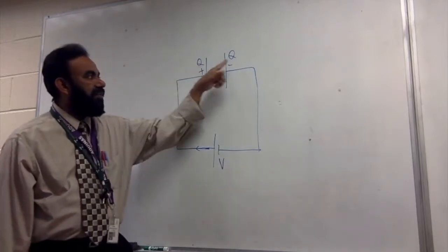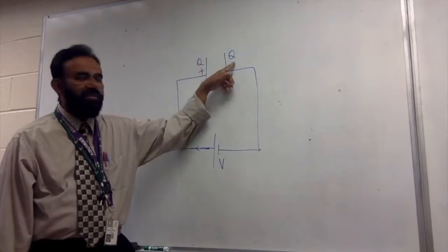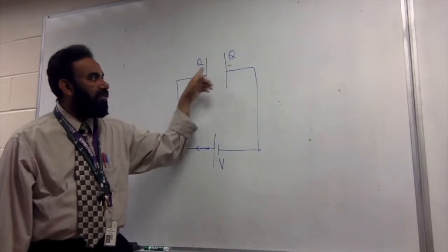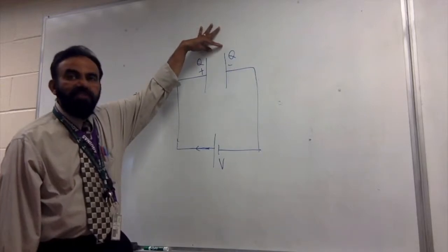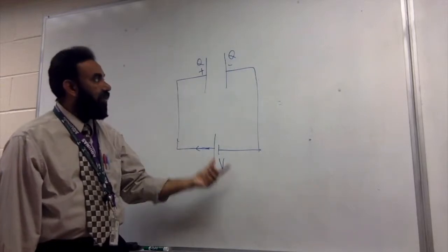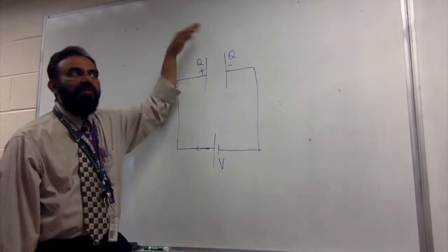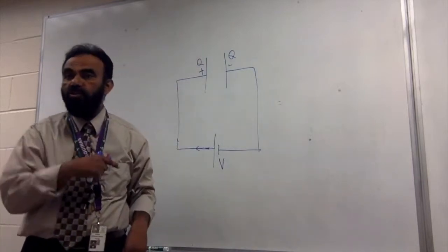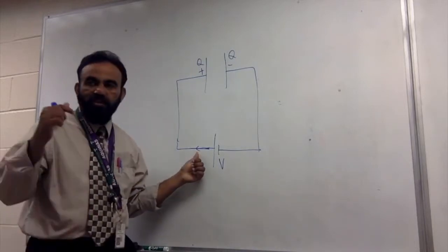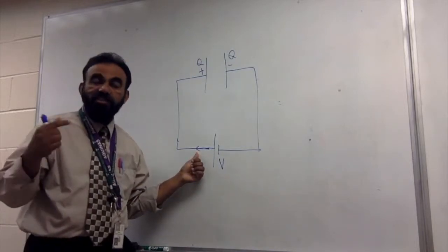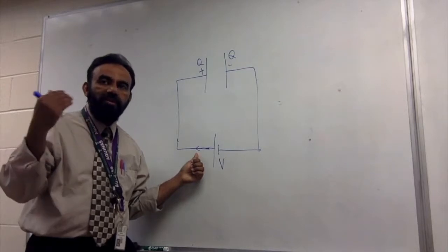And that is what charges this up. But as soon as small amounts of charge drop on the plates, it establishes a small potential difference. So this is 12 and that is 2 perhaps, and therefore the net potential difference is now not 12 anymore, it is lower. And because it's lower, this current will drop. So the charging current will start dropping.